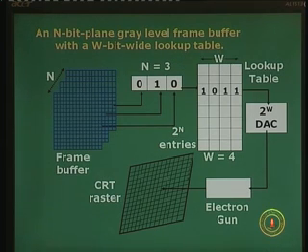That is interesting. Now the DAC, instead of being 2 to the power n bit wide, will have different levels from 0 to 2 to the power w. So it has more capacity than what the frame buffer can access, and that is an advantage, because now 2 to the power 4 is 16. So out of 16 possible intensities, you choose your 8, that the programmer chooses his 8 possible intensities,